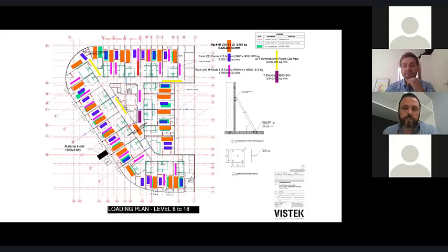Yeah, and just before we jump to the next slide, Nath, you also need to consider the need for cladding all of this material. So we've had to load a lot of plasterboard in. And when we talk about costing of this type of structure, you need to also consider potentially spanning across 2 floors and then leaving a potential wall out. And whether that works structurally, whether you have the depths to span that far, all needs to be analysed.